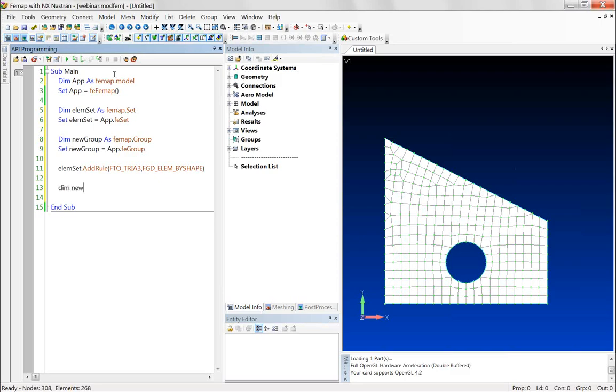Next, we'll create a variable to store an ID for the group that we've created. And the next empty ID method of the group object returns the next available group ID in the model. And we'll use that for the new group. This will just be one as we don't have any existing groups in the model. But if there was a group with a number 1, it would automatically place it into ID 2. Okay, this will be important when we go to save the new group to the model.